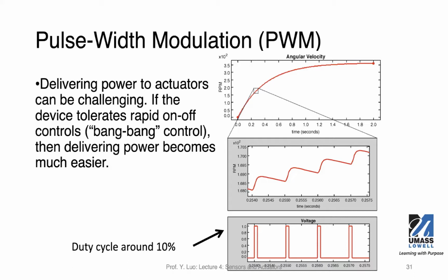The coil also has its inductance, which is kind of the opposite, trying to slow the movement down because of the magnetic field. So when you apply on and off control to this motor, the motor will turn, and even if you turn it off, it will still have momentum until you drive it next time using the next PWM pulse. In this way, the motor can turn continuously.